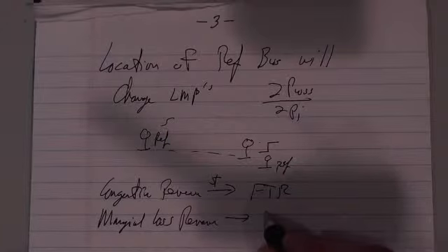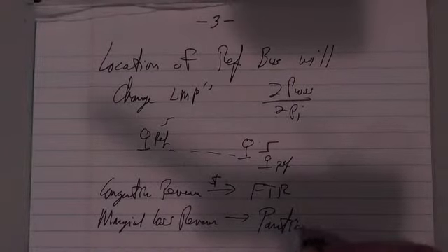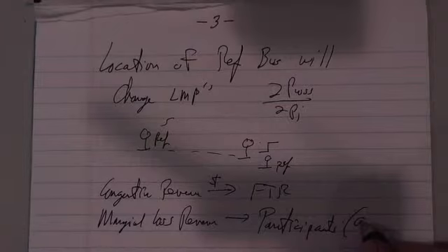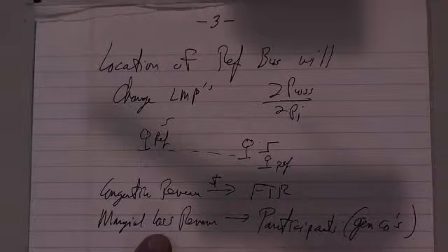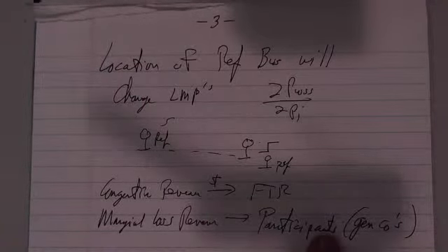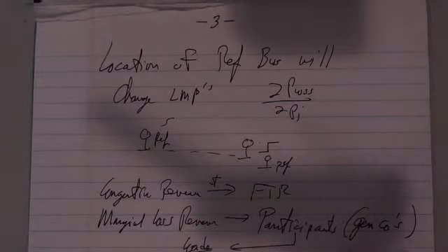goes to the participants based on hourly marginal loss revenue load obligation. Losses are nonlinear, so after paying generators for their extra generation that went to losses, there is some money left over that basically gets paid back to the load. So they have a way of paying this to the participants, mainly the generators. They get this marginal loss because they had to supply it, okay? And if they determine that the amount of revenue misses the target, then they may fold some of the money back to the loads. But they pay the generators for the extra that they generated.